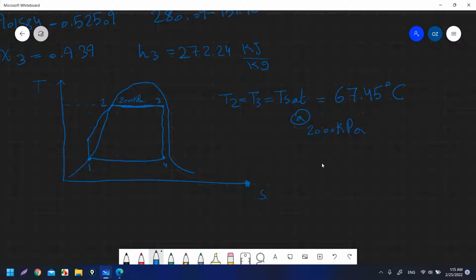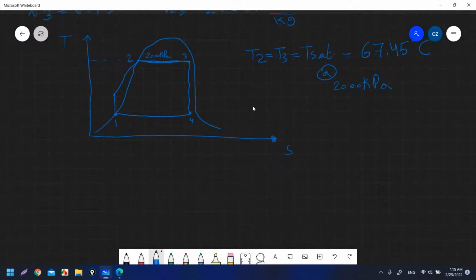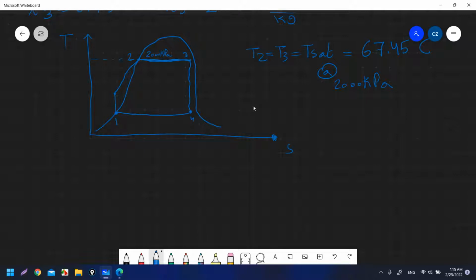Okay, and as you can see, it is better for us if we have reheating, not reheating, superheating. Reheating is another thing. We will have a cycle about reheating in the Rankine cycle. We have superheating, because this area is like this shape, right? But if we have superheating, it will be like this shape, and we'll move a little bit further here to reach the saturation vapor line, and we'll go up with superheating, and then we will go down.